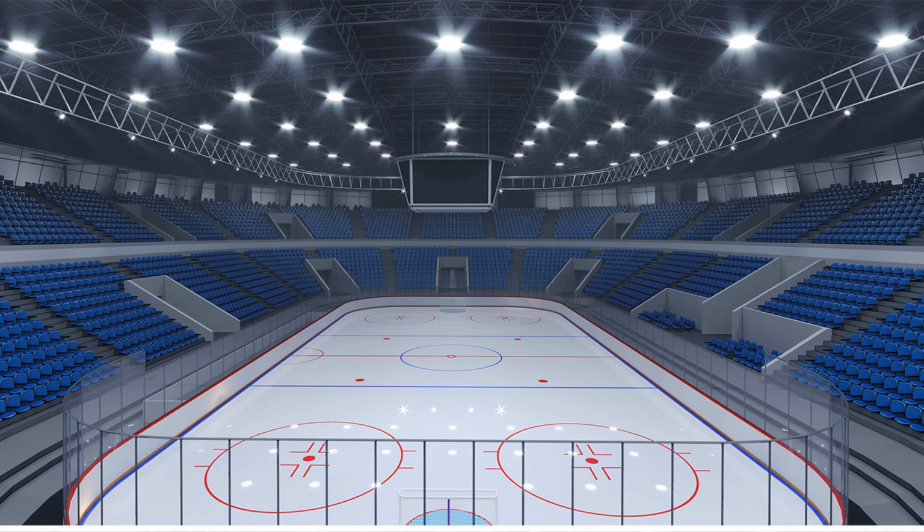And then glare control. Glare can impair both athletes' and spectators' vision. This is especially important in areas like courts or fields with overhead lighting. Your fixtures should be positioned and shielded to minimize direct light into the eyes of players and spectators, especially in areas like the stands or during broadcast events. And the ability of a light source to reveal the true colors of objects is essential for a sports facility, especially for televised events. So the color rendering index, or CRI, measures how well light sources render colors compared to natural light.